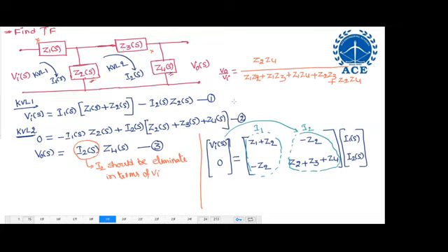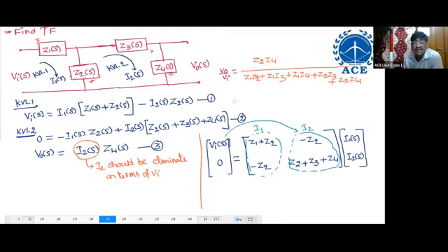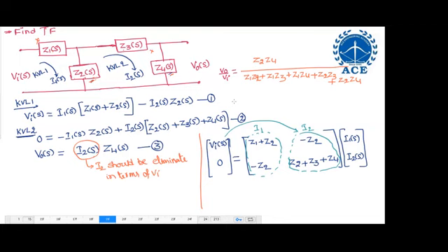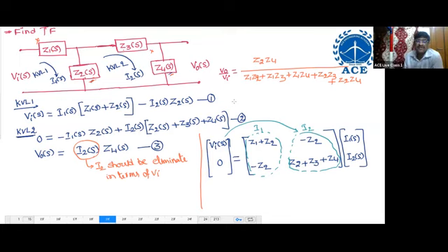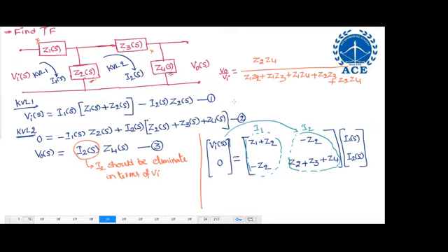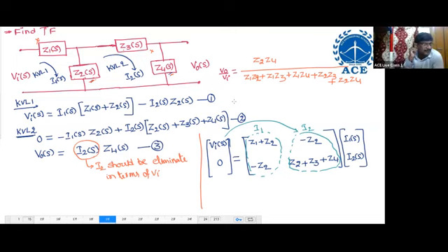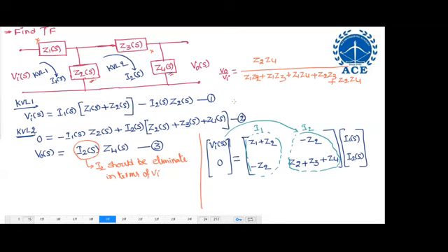Good evening, sir. Sir, how can a high gain result in an instability problem? If we increase the gain, how does stability decrease? That will come in the root locus. Roots basically shift to the right: as K increases, generally the roots move to the right. It will come in the root locus. Okay, sir.